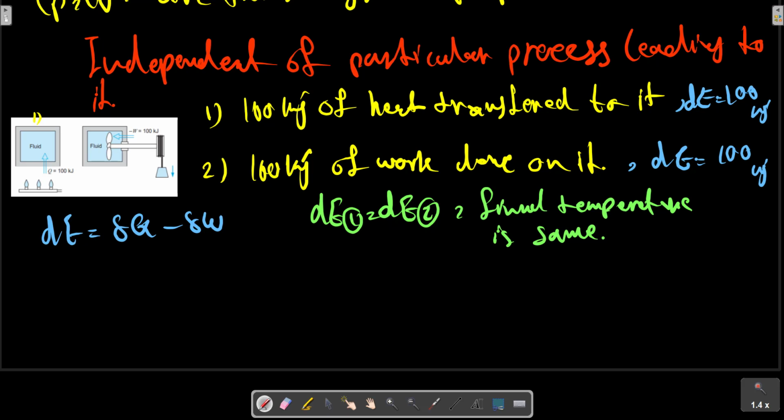In accordance with the equation for the specific heat at constant volume, exactly the same value for the average constant volume specific heat would be found for these two processes, even though the two processes are very different as far as heat transfer is concerned.